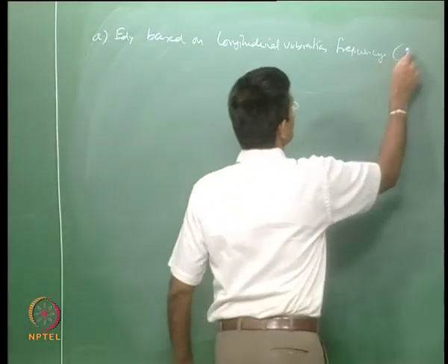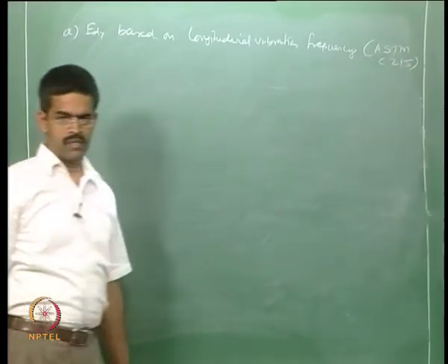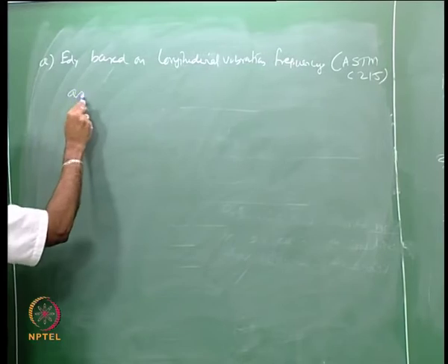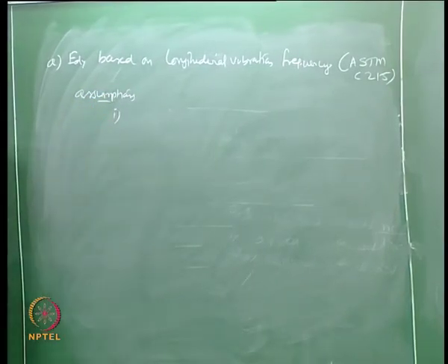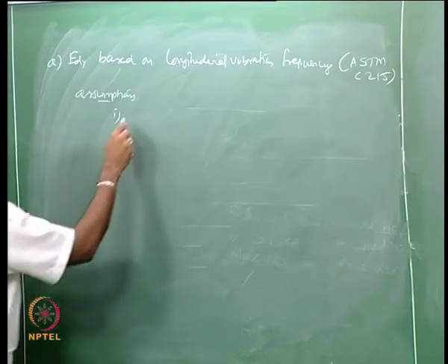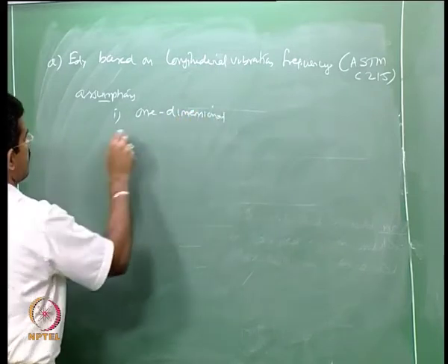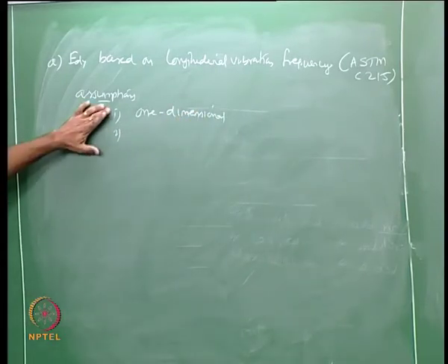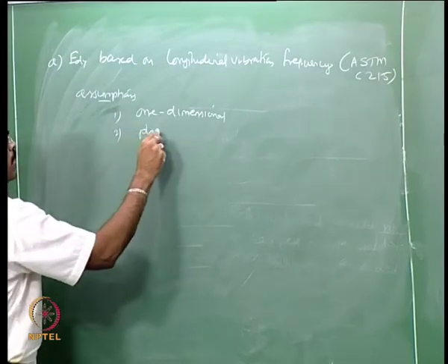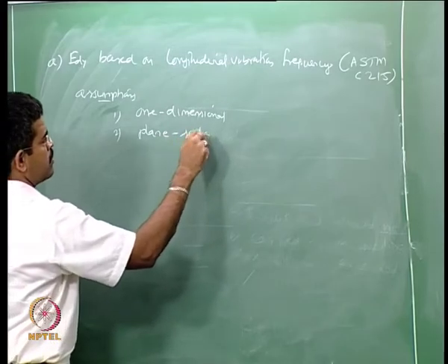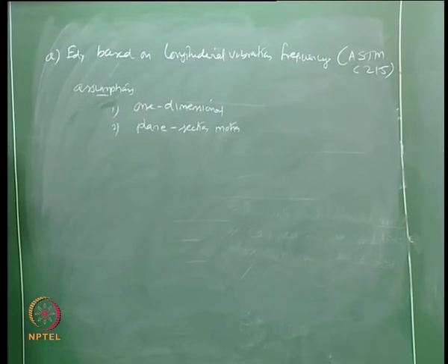This is based on the ASTM C215 technique. There are certain assumptions for this experiment. It is one dimensional, it is a plane section motion, and there is no distortion being invoked in the material.